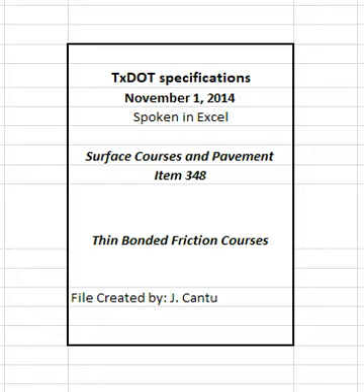4.3 Quality Control Plan, QCP. Develop and follow the QCP in detail. Obtain approval for changes to the QCP made during the project. The engineer may suspend operations if the contractor fails to comply with the QCP. Submit a written QCP before the mandatory pre-paving meeting, when directed. Receive approval of the QCP before beginning production. Include the following items in the QCP.